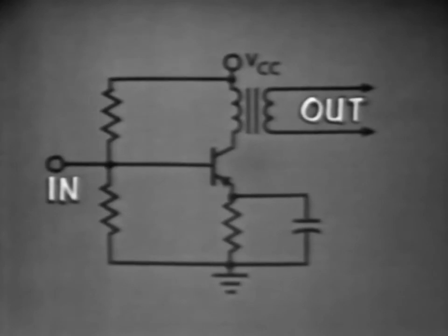Any amplifier will oscillate if feedback occurs. But what is the frequency of oscillation? In the LC circuit, we found that frequency is determined by L and C in the tank. Now, the same thing is true in the amplifier that oscillates. But since there is no frequency-determining device, the frequency of oscillations is determined by distributed L and C. That is, the input capacitance of the amplifier, the inductance of the leads, or any inductors and capacitors in the circuit. Very difficult to predict the frequency.